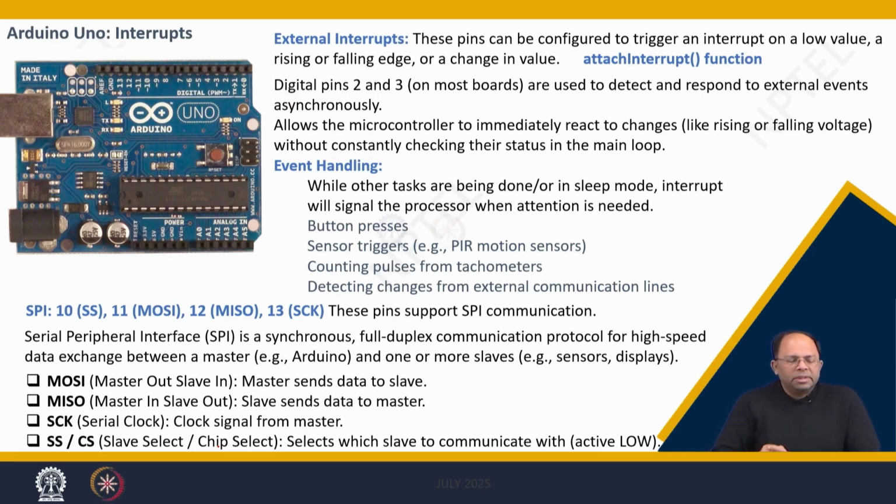Then there is something called interrupts. That means any kind of circuit sometimes requires interrupts. For example, in one of our products, we have developed a system where there is an accelerometer connected to an Arduino, and if somebody moves that system, immediately it wakes up the microcontroller. Usually the microcontroller is in a state of sleep, or it may wake up some other sensor, like for example a GPS location.